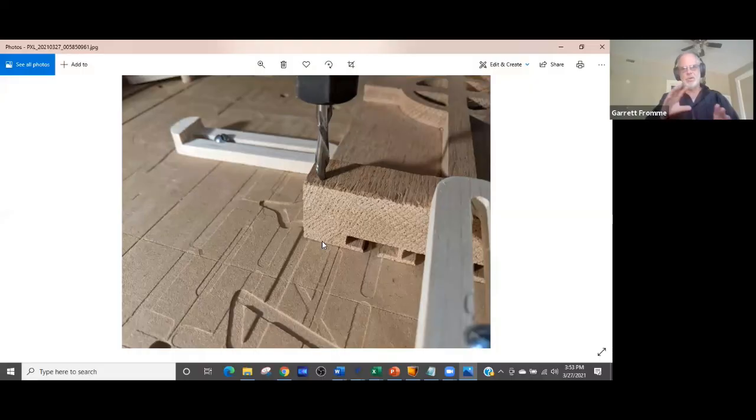The post processor doesn't really do this. This is the controller, and this is, I believe, where Grbl comes in. There is a known limit that your machine can travel. If it's a Bob's, it's got limit switches. It might have what do they call them, sensors where it detects when it gets close. And then it's got some stroke.